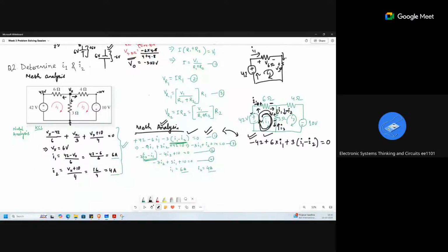Where the current enters, there is no fixed polarity of the resistance, so we should consider it as per Ohm's law. If current I1 enters a resistance in this direction, then the potential difference is created from positive to negative, which can be written as V1 equals I1 into R. Suppose I know the potential is generated plus to minus, but my current flows from the other direction, let me call it I2.